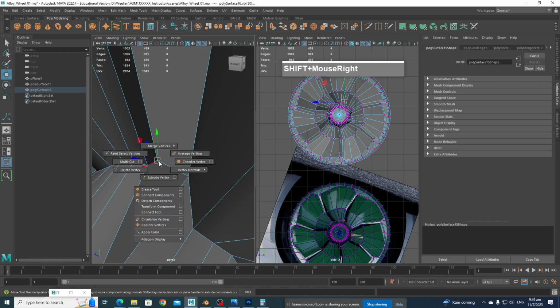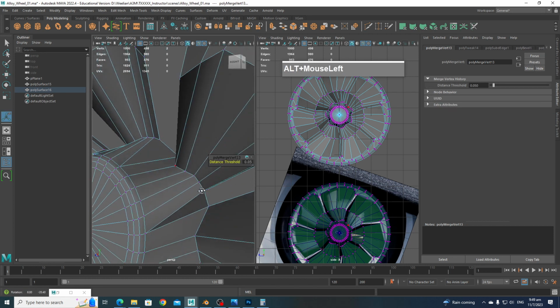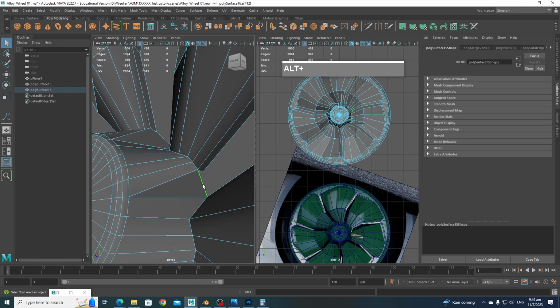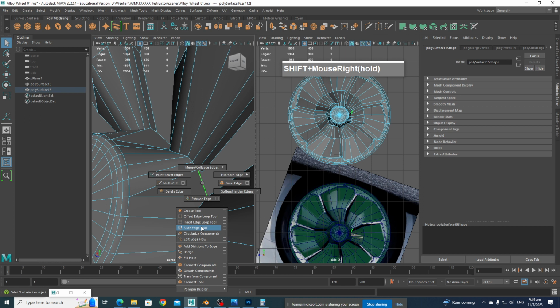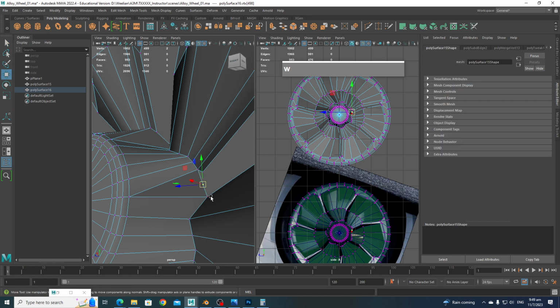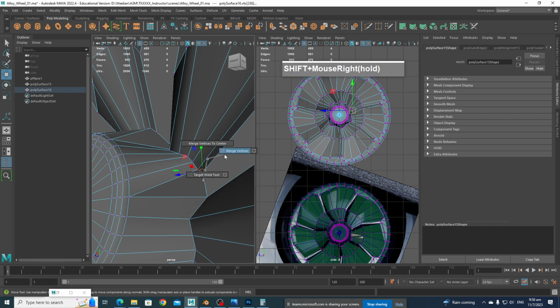Then I can merge these two together. So right now, I'm just doing some cleanup work here. So again, go to the edge here, then shift right mouse click, subdivide, add one subdivision so that there is a vertex in the center here, and then holding down V with move stage, select these two, merge the vertices.